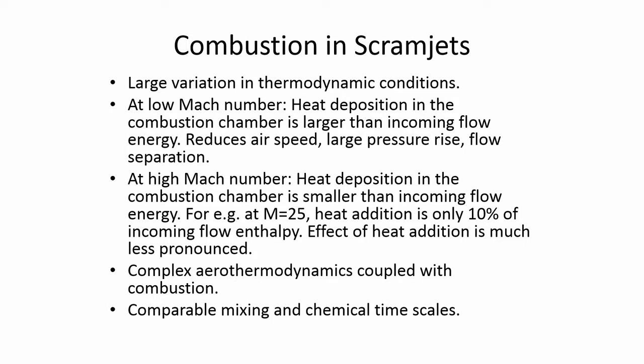Okay, as I said before, in a gas turbine combustor the flow is essentially conditioned by several things. It passes through a series of compressor blades, rotor and stator blades, then it comes through the diffuser, and then it goes into the combustor. So the combustor entry conditions are pretty much well defined. They cannot vary too much.